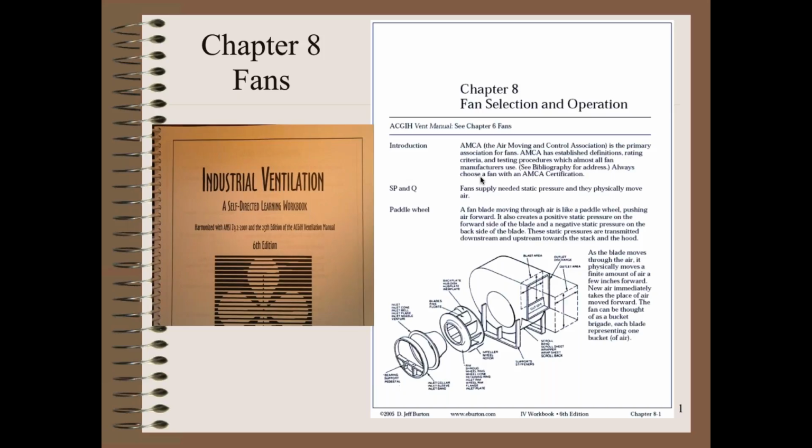So what does that tell you? This tells you how much energy you have to put in to get the air moving and to cover any losses on the suction side and on the discharge side. That's determined by your static pressures on the two sides of the fan. And the Q is how much work you're doing, right? You're moving 2,000 cubic feet per minute of air. That's work. There's so many pounds of air that you're moving at a certain velocity. So you combine those two, and you can figure out how much horsepower, how much energy, how much work you're doing.